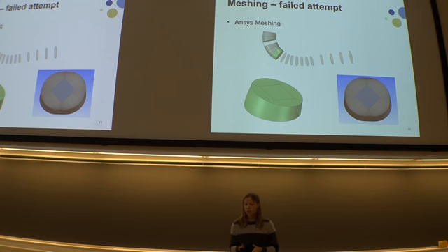So what I tried to do then was to have very many cross-sections that I transfer into volumes, and inside every cross-section I created a square prism. So I was able to control the number of divisions when I used the meshing tool. And that turned out to be very manual work. And worst of all, it's not scalable. So I will not be able to use this approach for doing design optimization.